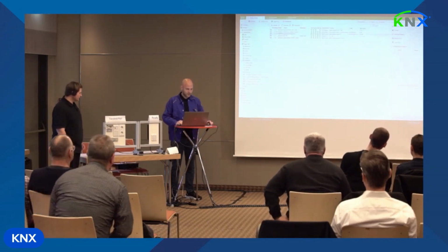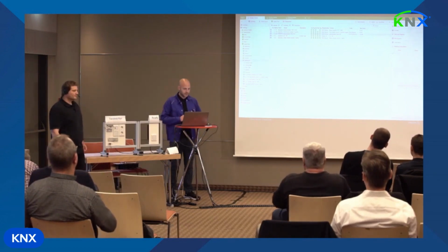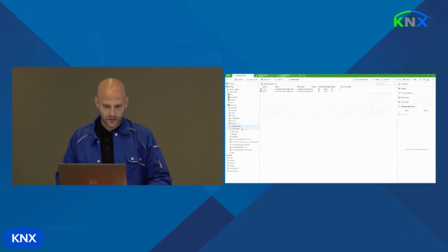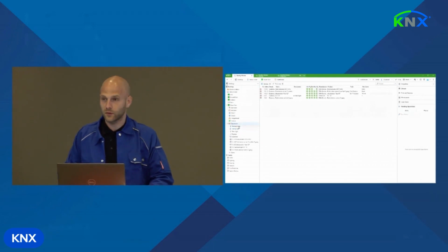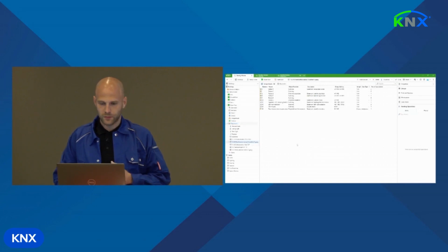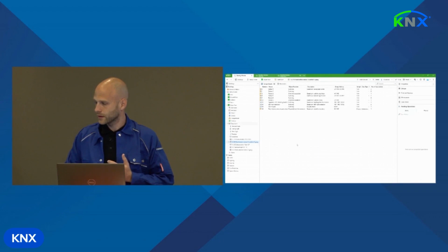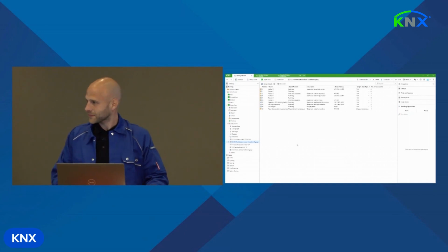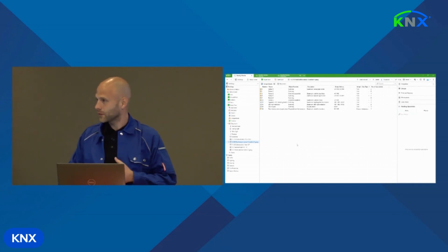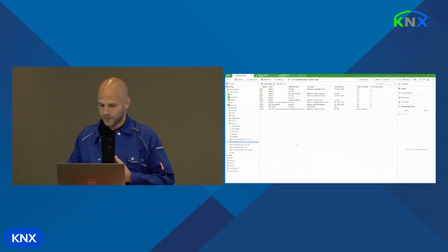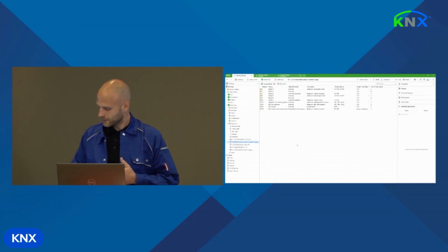So what I have here in the family home project, in the building's view, I see an ambient light and a ceiling light in the guest room of the upper floor. And on this push button, we have both lights linked through group addresses. And this works. So do I understand you correctly that this is our guest room? This is the guest room. And you have extended this with radio frequency? Yeah. There's a remote control device with which you can control radio frequency lights and lights conventionally connected through twisted pair. Correct. Can you show me?